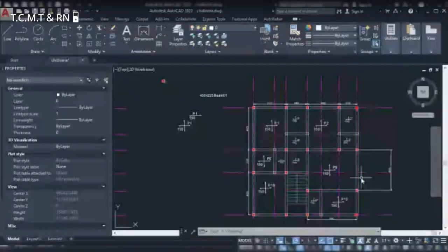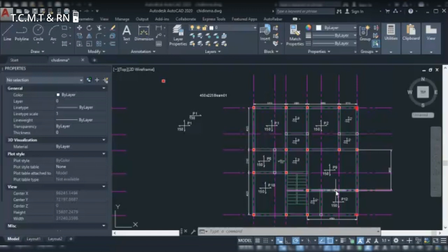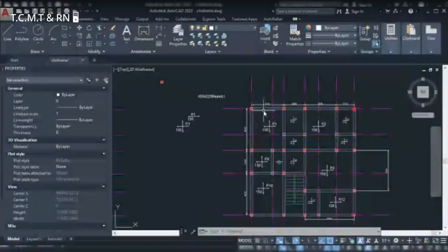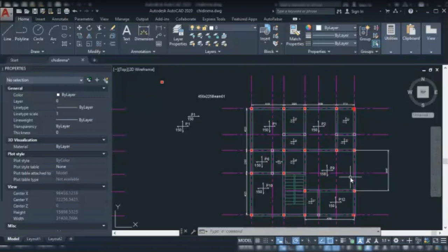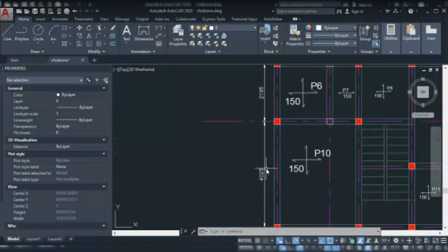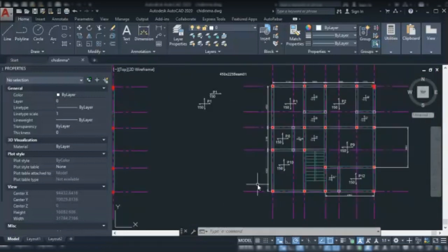So we are using the worst case condition, the longest beam. Then you choose your size of section. Once you make that size, you use it for the whole beam. I think the longest should be this one here. Once you use this one, you have to fall within this 450. So we're going to be using 450 as the depth for the whole beam here.